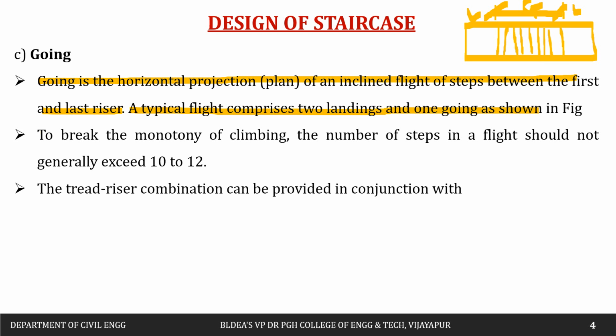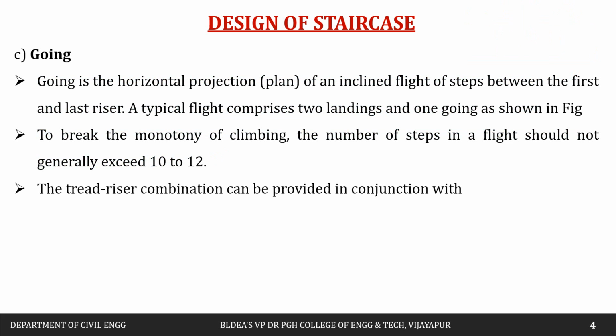To break the monotony of climbing, the number of steps in a flight should not generally exceed 10 to 12. So instead of keeping all 20 to 24 steps at a stretch, so as to avoid the monotony, we divide them into 2 or 3 flights.